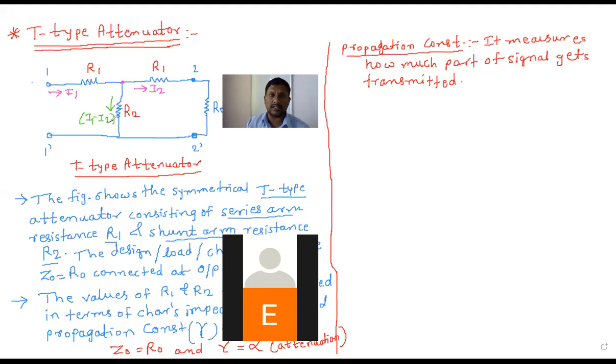I will mark all the currents here. According to these currents, I will mark the polarity of the voltage drops. This is plus minus here, and this is plus minus here. According to I1 minus I2, this is plus minus here. According to I1 here, this is plus minus here. So I will mark the polarity. Now apply KVL in the loop. Okay, so I will mark here.